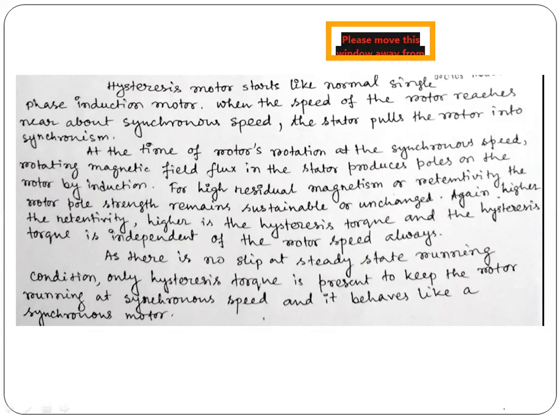As there is no slip at steady state running condition, only hysteresis torque is present to keep the rotor running at synchronous speed, and it behaves like a synchronous motor.